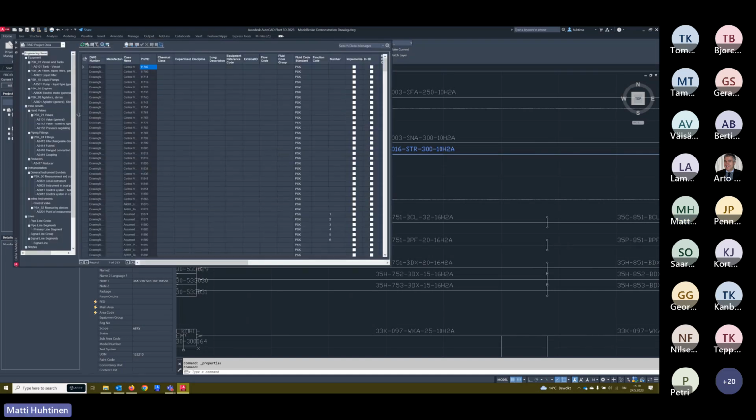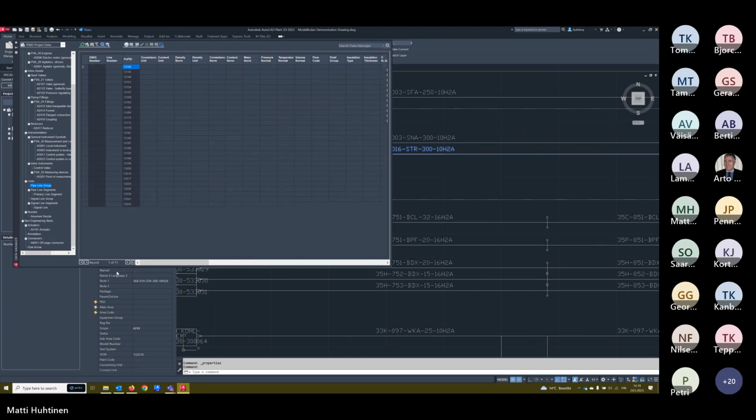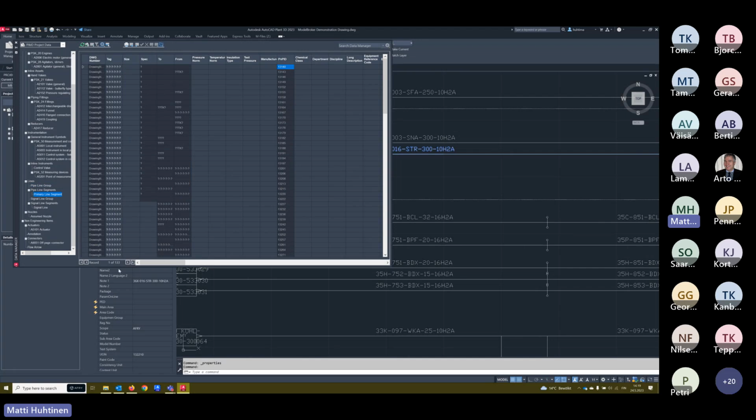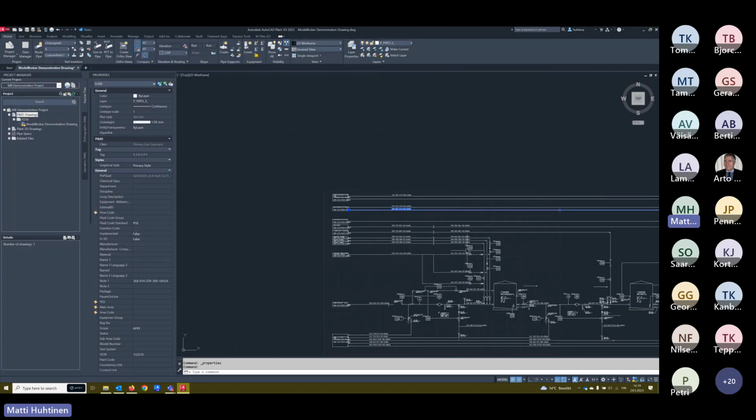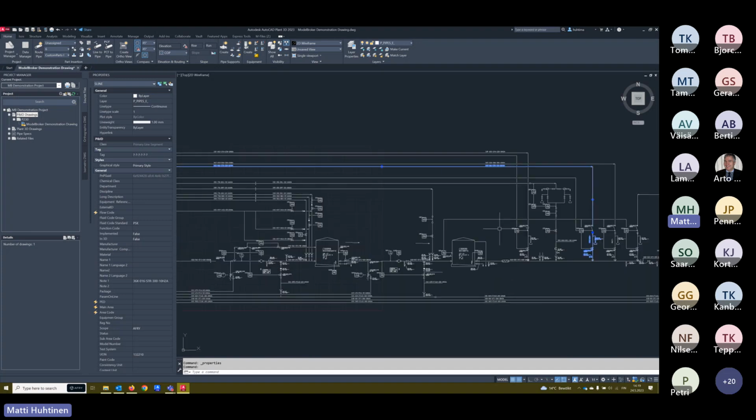Now we have everything here in place. We have tanks here, we have filters, we have pumps. In this drawing, we have 11 pumps. We have 133 lines, and of course we have more segments. So we have 154 segments, but everything is in the Plant 3D database. And now I can continue that. I can edit this diagram and continue, or I can use it just like this.